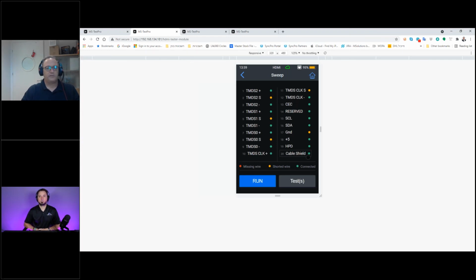Why is it a problem? Think about the engine that was starting to work next to the HDBaseT. You're seeing immediately an artifact that is being injected directly to the HDBaseT, and you are seeing failure, a video drop. In the case of HDMI, if you are getting those artifacts directly to the shield, the shield will short it this way or another.